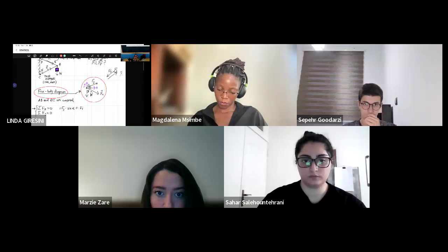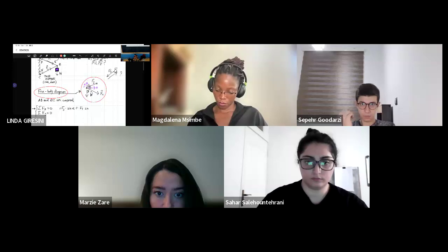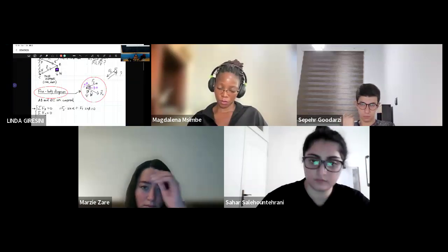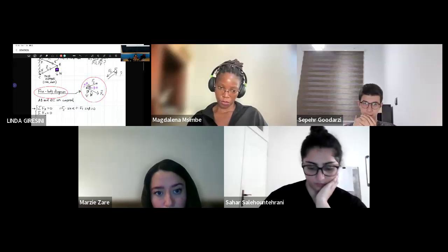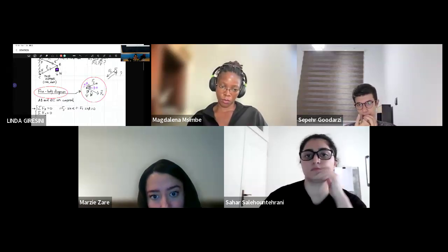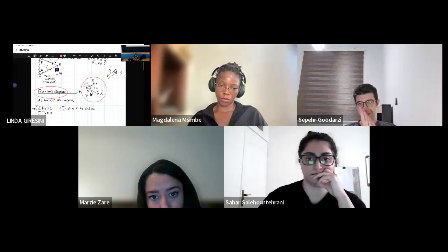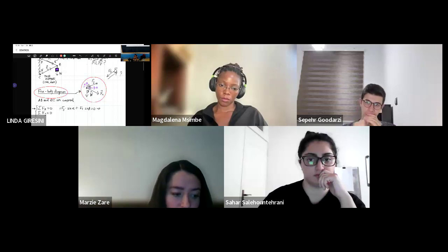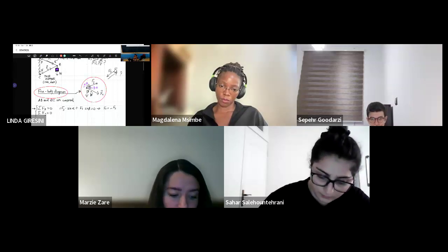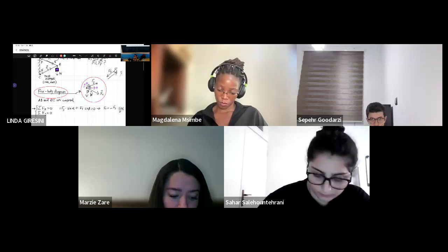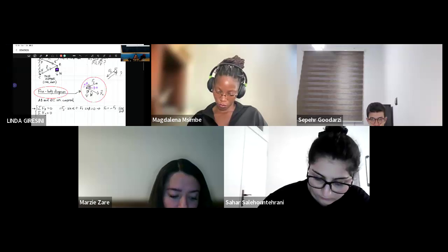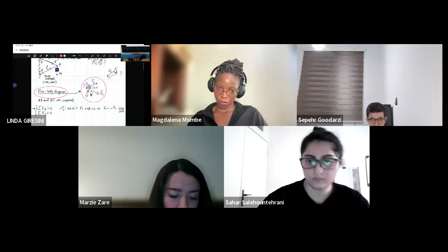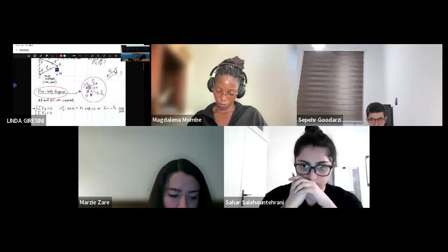Sine or cosine? Sine. Sine beta equal to 0. So this is the first equation for horizontal equilibrium. In any case, if from this we want to find, for example, F1, F1 will be minus F2 times sine alpha divided by sine beta. So if the negative sign appears, it means that the direction is wrong.